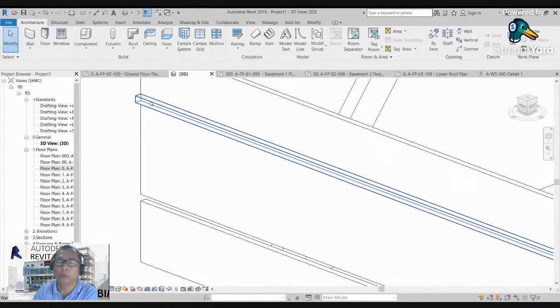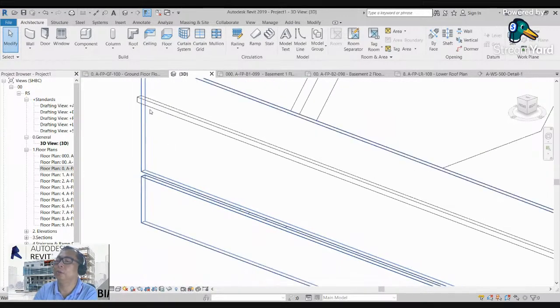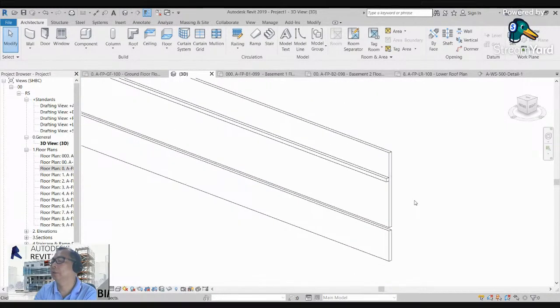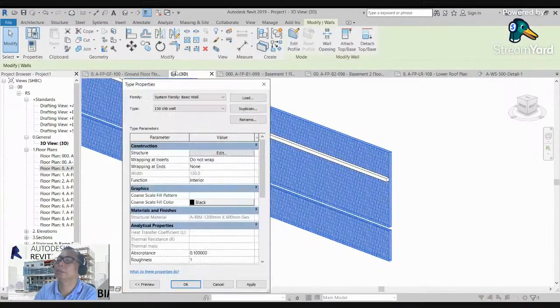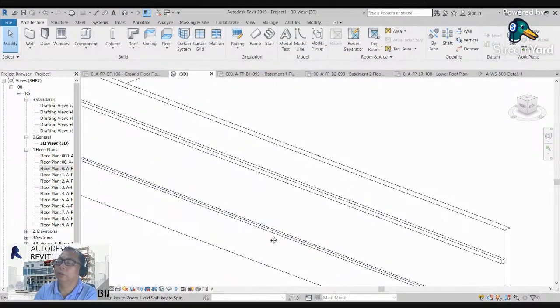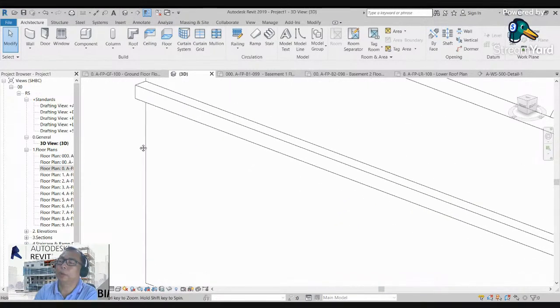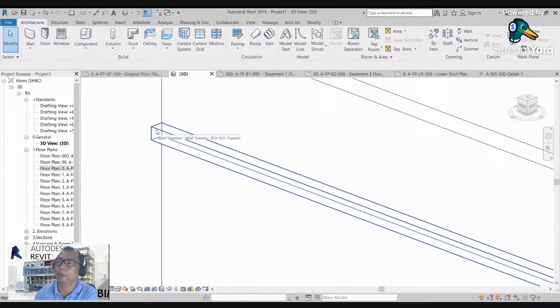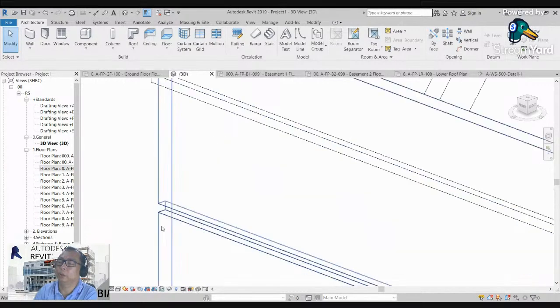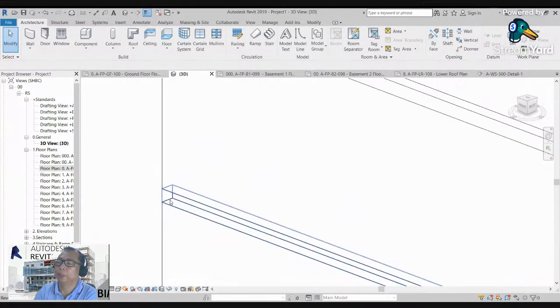The other is exposed. The other is inside. This is outside. Revealed. See? I'll change this thickness to 300. It's better. See? Also, you can change also the profile of this. You can create the moldings for this external moldings, or inside the wall internal molding.